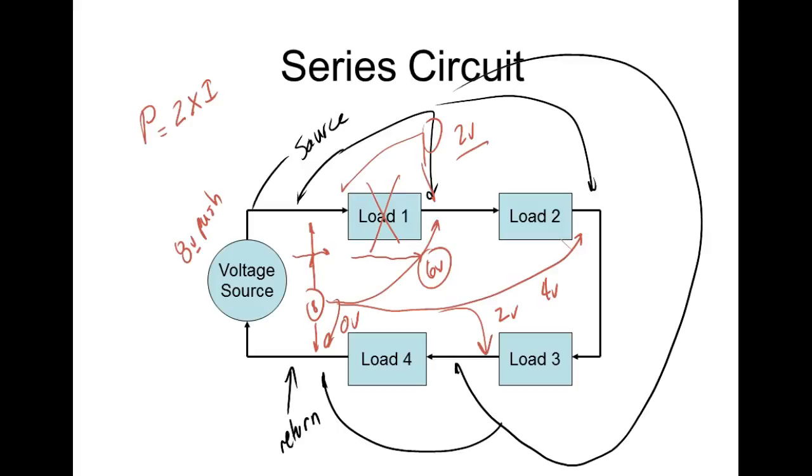But instead of me having a big old bulb that's rated at 120 volts, I can have a lot of small bulbs that might be rated at 8 volts, right? You understand? And then how many would that be? Let's do 4 volts. That'll be easy to calculate. If I put 30 of them in series, then together they would drop 120 volts. So that's why if one of them goes out and you short it out, all the rest of them get a little brighter and they'll start going out, because now instead of dropping 4 volts, they're dropping more volts, right? You understand? So that's the biggest disadvantage of a series circuit.